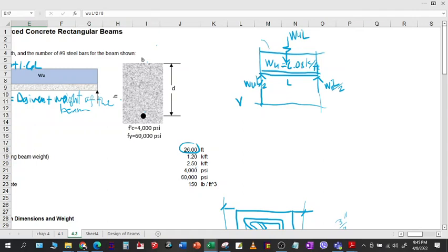And then this one is 0 degree. This is a horizontal line, so this is 0 degree. So the shear will be on the first degree. The shear is a first degree curve. So a first degree curve is a straight line with a slope. So the slope goes downward because the load also goes downward. Okay? If I may draw the arrow here, since the load is going downward or negative, then the line here also goes downward. This is first degree curve.